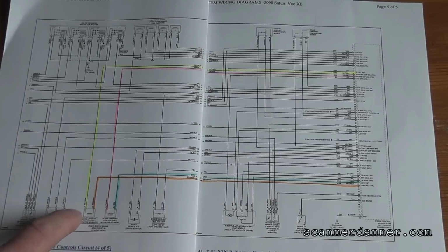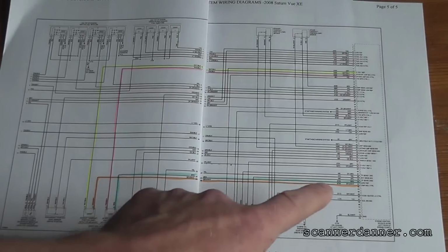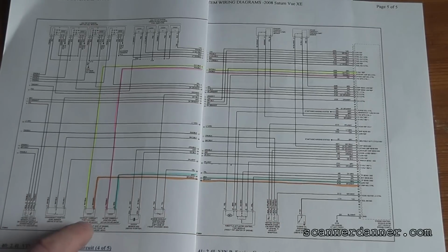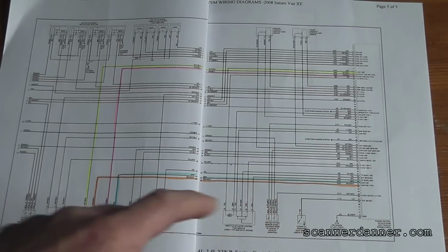So focusing on the exhaust, that's our trouble code. The yellow and orange wires that I've highlighted, notice that they both go to the computer. Now what I say in section 3 in my book as far as identification goes is you follow the wire that doesn't go to the computer, and that will tell you the circuit design. If one of these two wires goes to a ground, an external ground, that means it's power side switched, meaning the other wire going to the computer would be power.